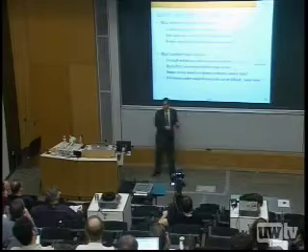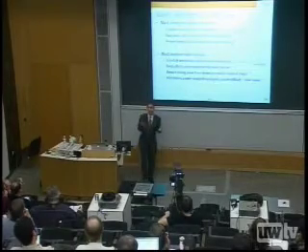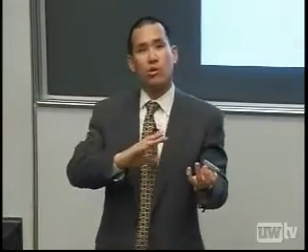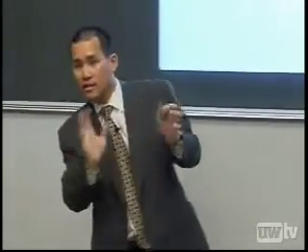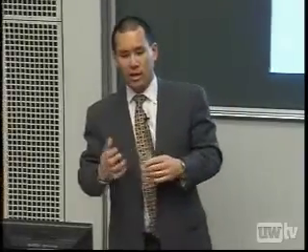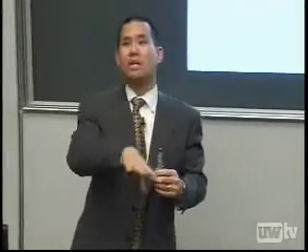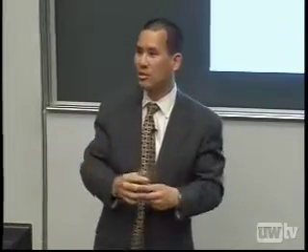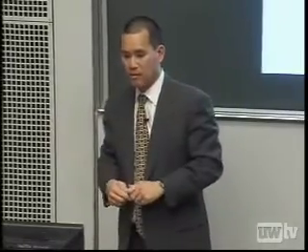There are a few interesting challenges because it's all about capacitance, right? And these coupling capacitors are not very big. They're on the order of 8 to 10 femtofarads, which means any parasitic capacitance on the far side of the plate directly cuts voltage signal. That's not a very pleasant thing. So you've got to make sure that any kind of backplate capacitance is minimized. So metal fill, be wary of that. So make very clever metal fill patterns that don't increase the backplate capacitance.